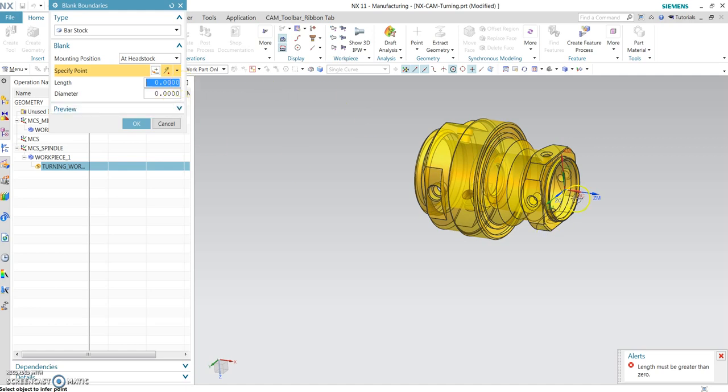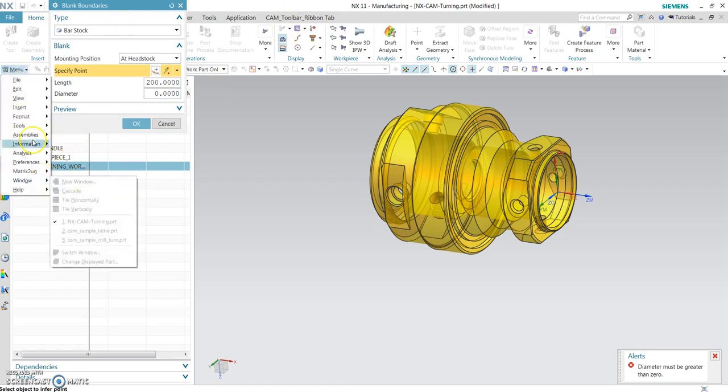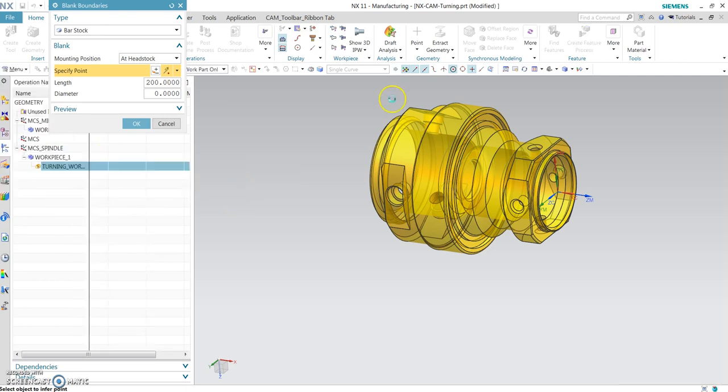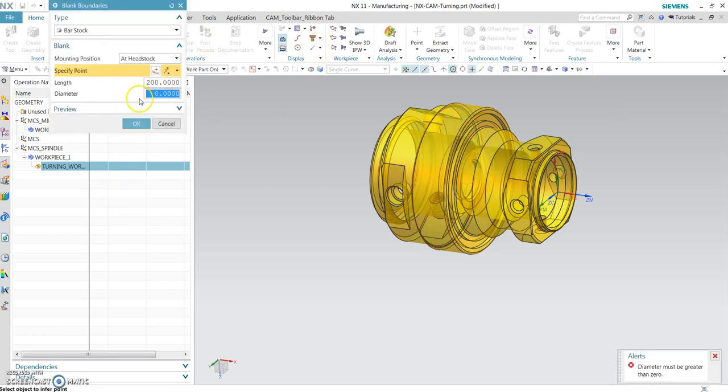Need to select a length, however you want it. So if you have 200 millimeter, we need to find out what's the radius, so about 142.87. So let's call it 143 on the radius. So it's going to be 286 on the diameter. Since for a cleanup stock, let's get 288.